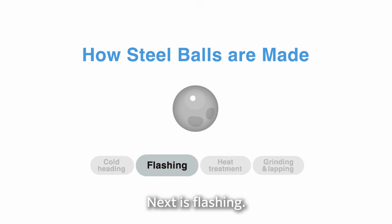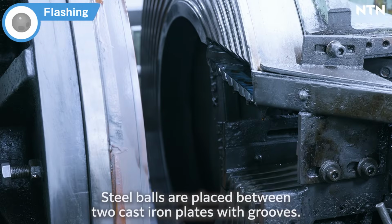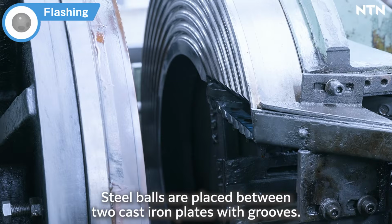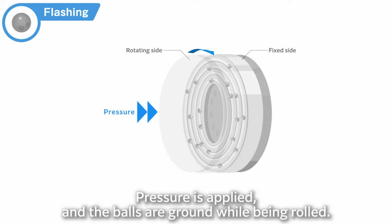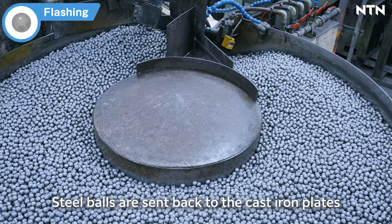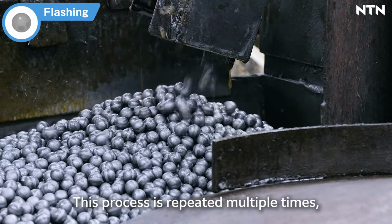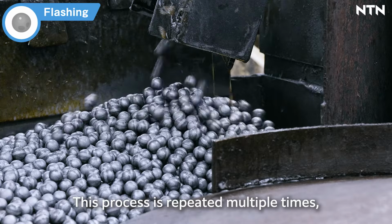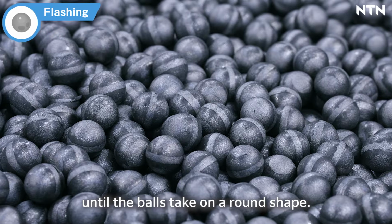Next is flashing. Here, the flash left from the cold heading process is removed. Steel balls are placed between two cast iron plates with grooves. Pressure is applied and the balls are ground while being rolled. Flashing is not completed in one step. Steel balls are sent back to the cast iron plates by an automatic feeding device. This process is repeated multiple times, gradually removing the flash from the surface until the balls take on a round shape.